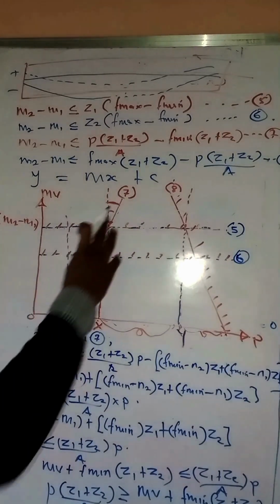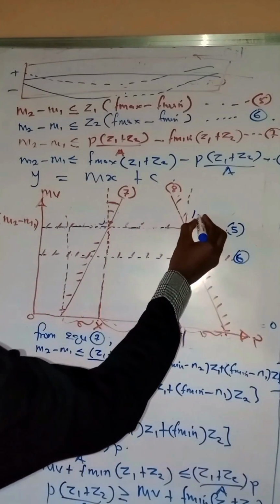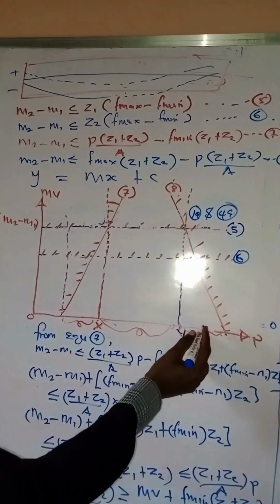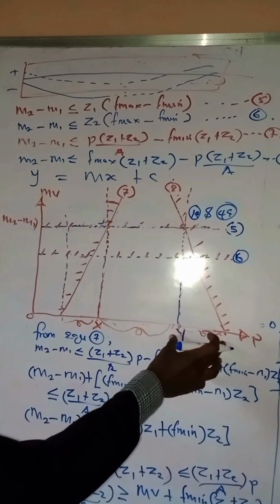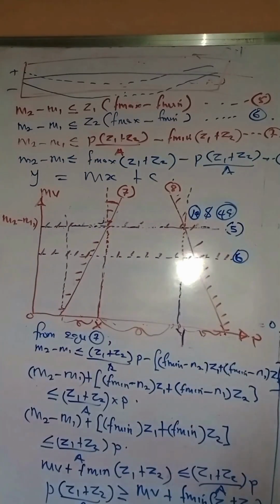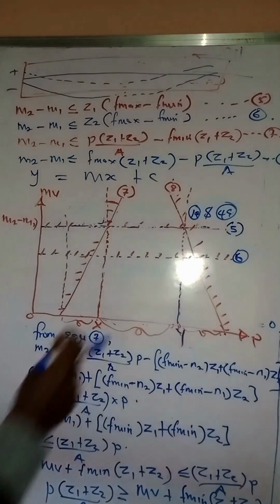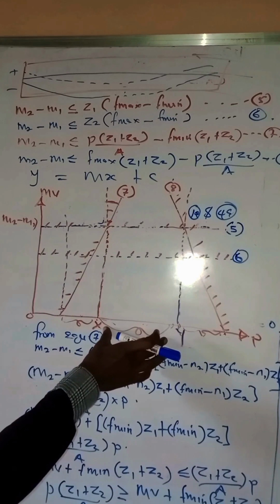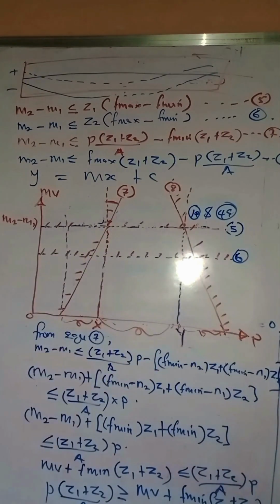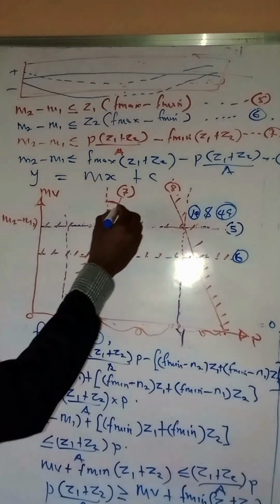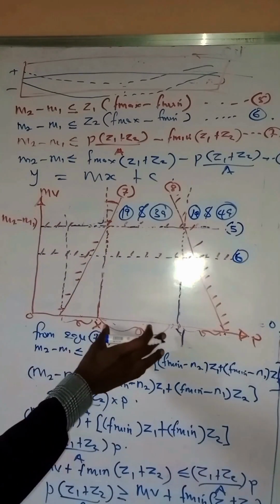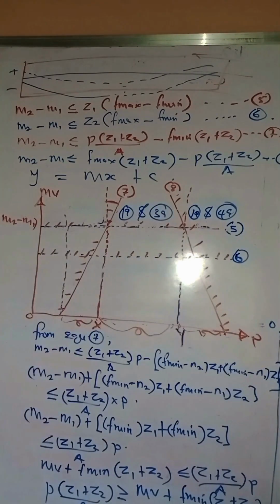Looking at this zone, here we are going to have equation 1A and 4A. So whatever pre-stressing force you are picking from this zone between Y to this point, the necessary cable eccentricity should be gotten using equation 1A and 4A. Similarly, when the pre-stressing force is gotten between X and Y, the necessary cable zone equation should be equation 1A and 3A.